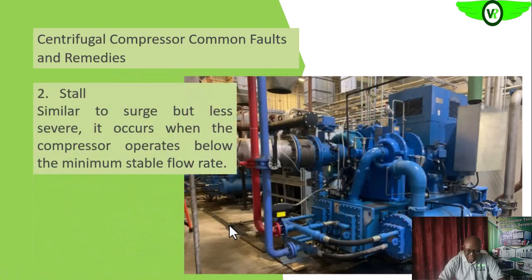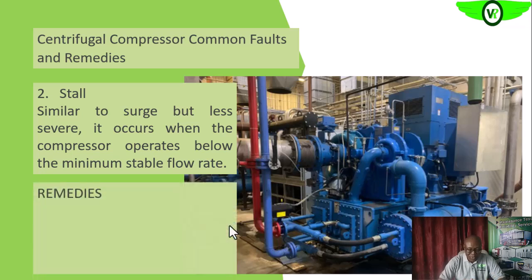Then, like we said, the other fourth condition, which is stall, is similar to surge, but at a lesser scale or less severe compared to surge. So it is basically the same thing. Okay, so we can remedy this by controlling, like what we did earlier, increasing the amount of gas that is taken off the discharge, relieving by opening up the bleed valve.